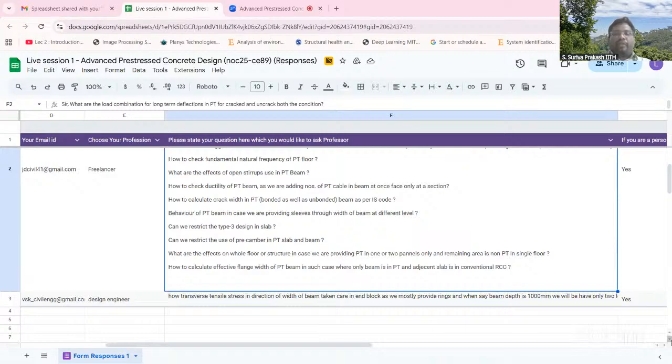So as we are adding numbers, okay. Again, see, the reinforcement is added wherever tension is there, right? The PT cable is also actually a reinforcement only, right? The only thing is the prestressing steel is also putting some compression in the concrete that is going to help you delay the cracking and improve the serviceability performance, right? There is no big difference per se, because the PT cable is actually a reinforcement only. Just like your singly reinforced section, you do the analysis, here also you do the analysis. For more details, you can look at the flexure chapter. We have discussed in detail how to do moment curvature analysis and how to do the analysis using strain compatibility, right? Hope it is clear?